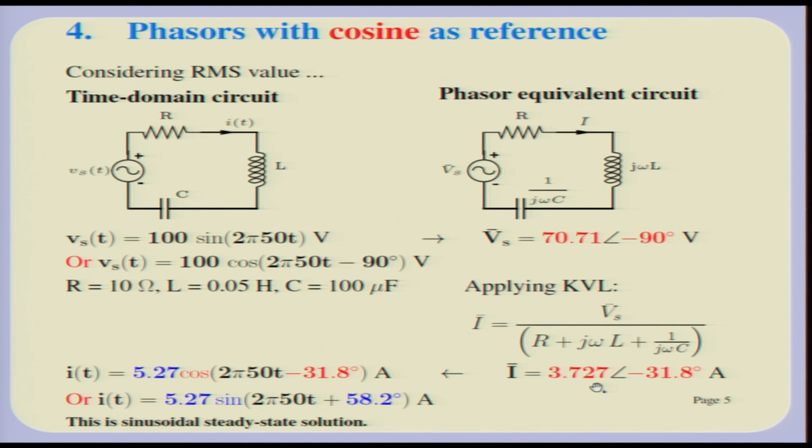So, for example, these are of course RMS values; the phasor convention here uses RMS values and not the peak values. You will find that in this case, since I am using RMS values, S will come out to be V I star here.